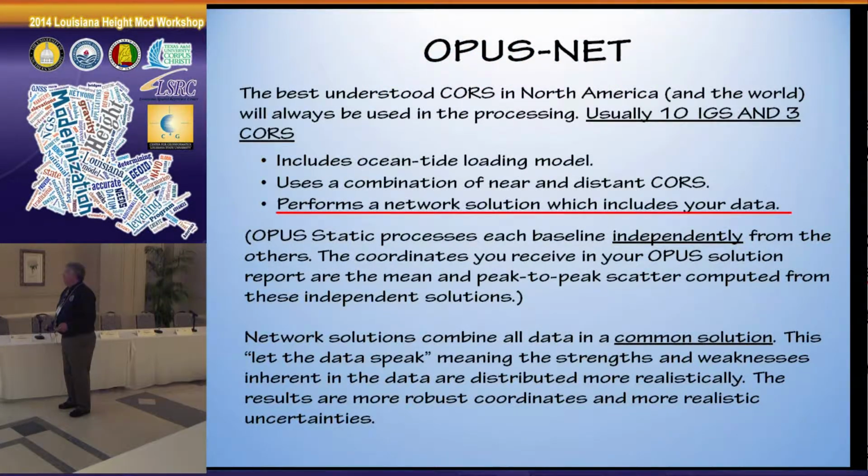OPUS-Net, again, just using global stations as well as local CORS. Not accessible yet, but what it does do is perform a network adjustment, like OPUS-RS.